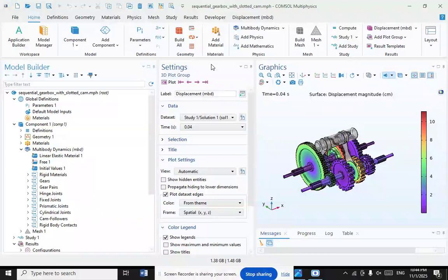These systems are based on the design of, and are technically similar to, a conventional manual transmission. They have a gear shifter which requires the driver's input to manually change gears, but the driver is not required to engage a clutch pedal before changing gear. Instead, the mechanical linkage for the clutch pedal is replaced by an actuator, servo, or solenoid and sensors, which operate the clutch system automatically when the driver touches or moves the gear shift. This removes the need for a physical clutch pedal.